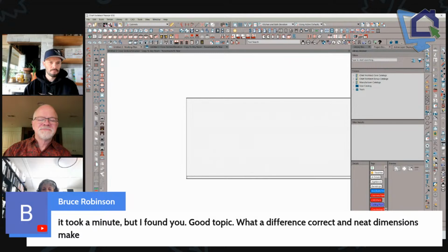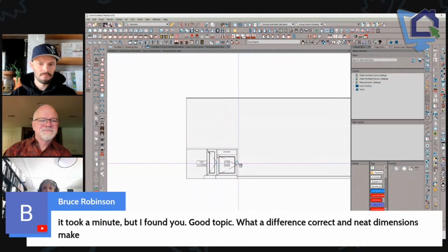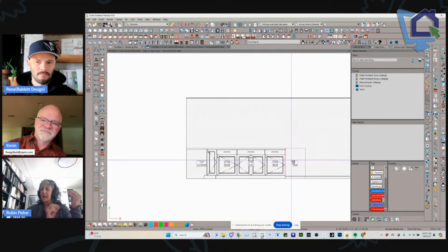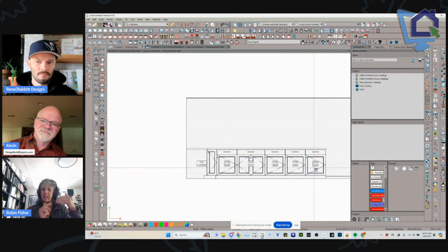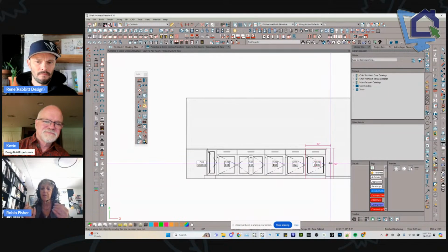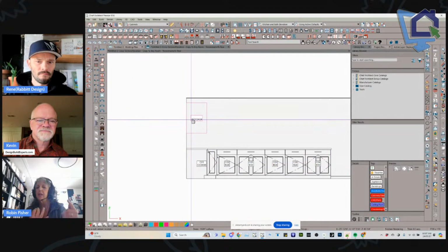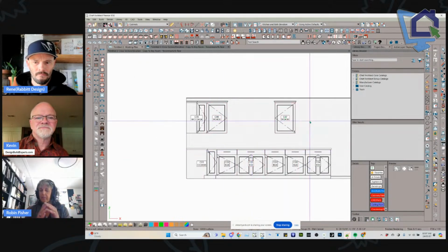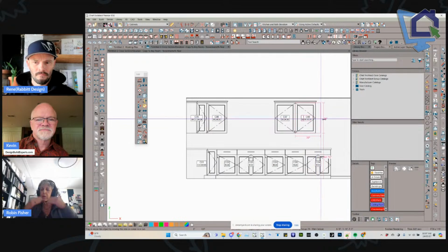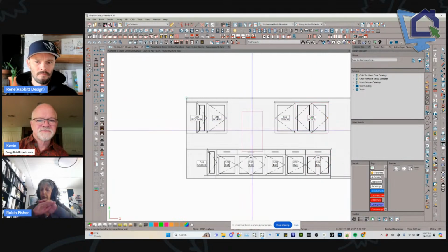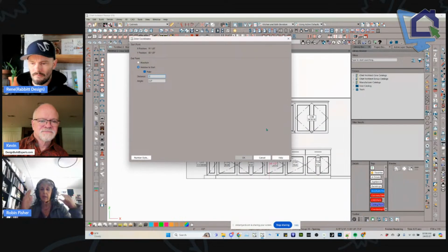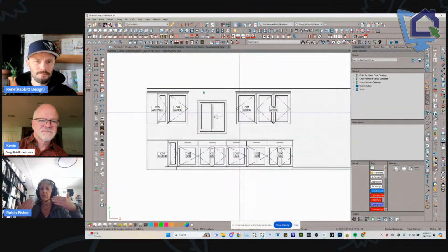When we are doing our elevations, the first line we want to dimension is cabinetry. So I have that set up to get to the sides of the cabinets. I don't do corners, I don't do center lines of it, but I do the sides of all the cabinetry. So when I'm doing elevations, my first line hierarchy, according to the NKBA, the first line is cabinetry, appliances, right? The sides of things like windows, that kind of thing. The second line is center line, third line's overall.